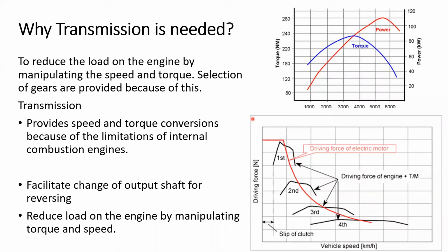Assuming it's an AC motor, then we can control the frequency of the electricity provided to the motor. By changing the frequency, again, we can change the speed, and by changing the speed, we can control the torque, right? Both of these methods can be used.